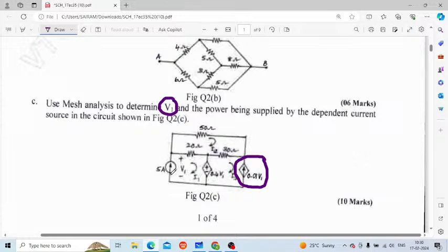You will get confused right here, first of all. Whenever you have I1 equal to 5 ampere, you don't go back to that mesh; you go on solving the next mesh. But here, this particular mesh also has to be solved using the superposition theorem. What you have to do is make these two currents open circuited and start solving according to the superposition theorem.